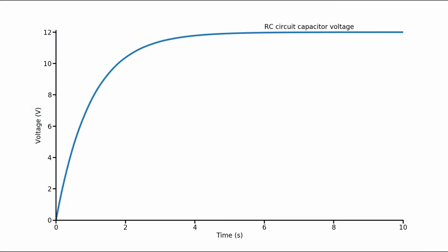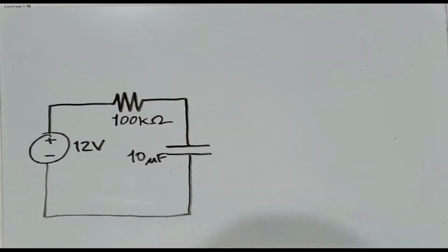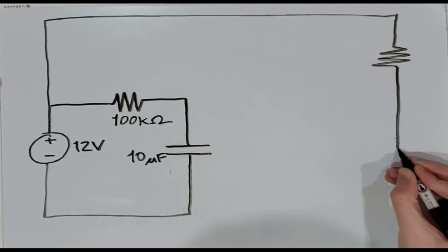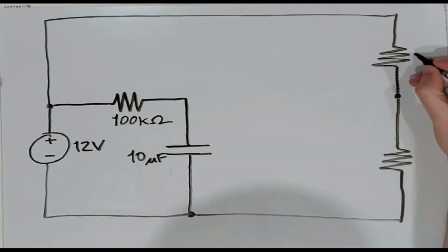For oscillation, though, we're going to need to periodically discharge this energy once the capacitor voltage hits a certain upper threshold. We'll create that upper threshold with a voltage divider over here, and we're going to make it a nice round 10 volts just because we can.